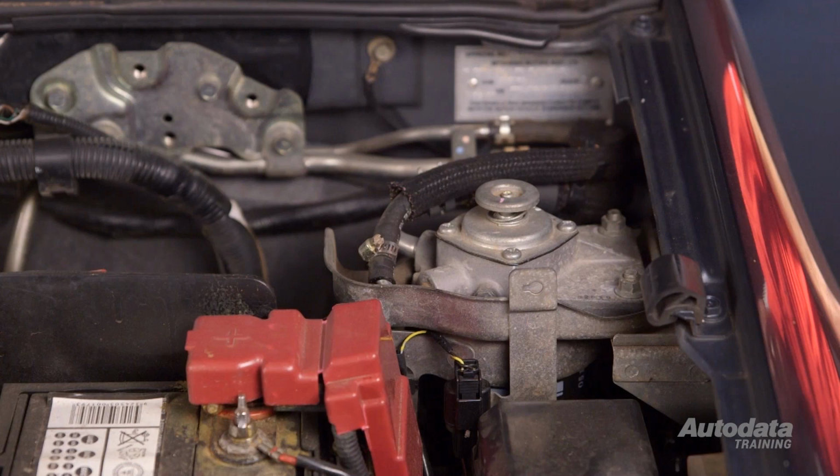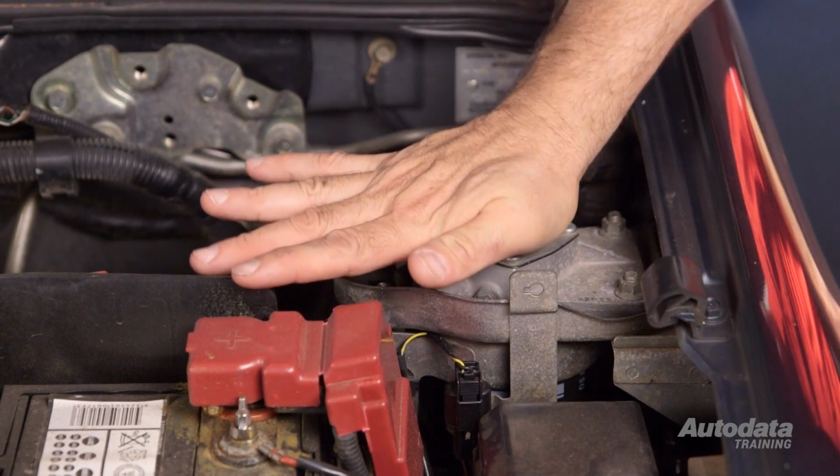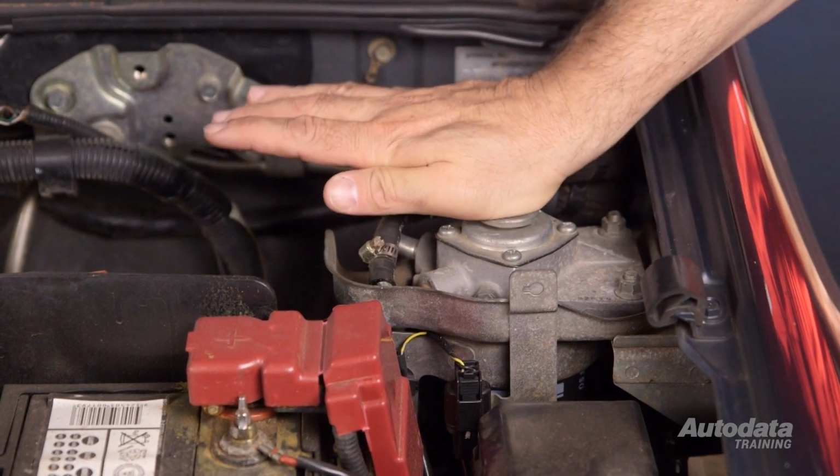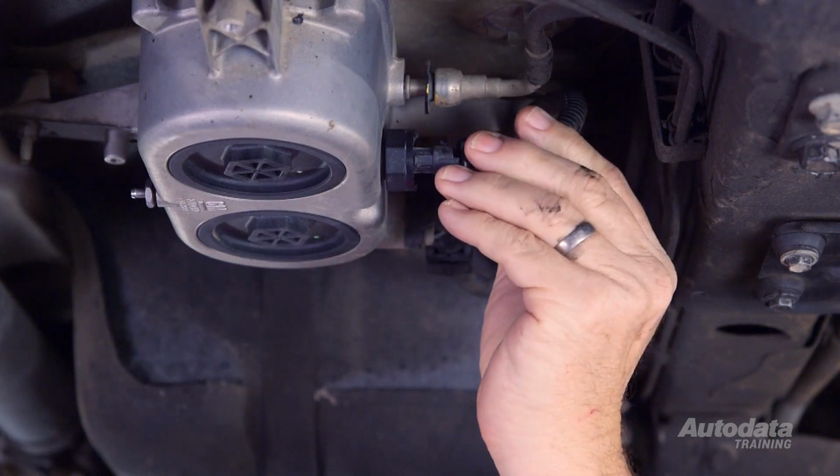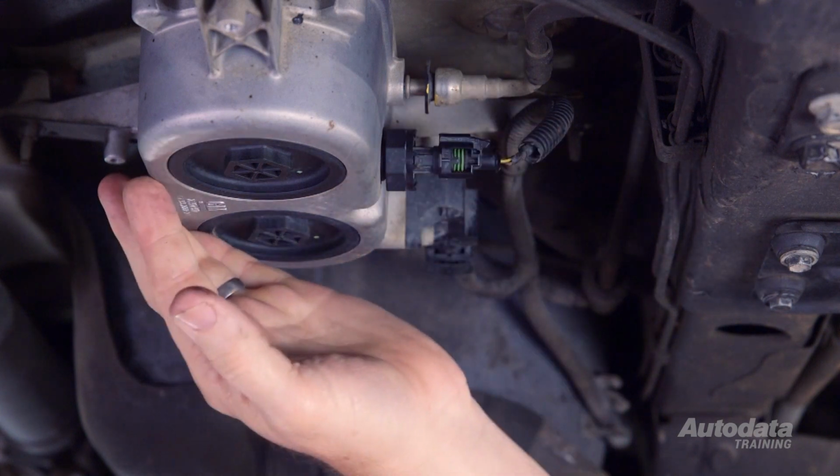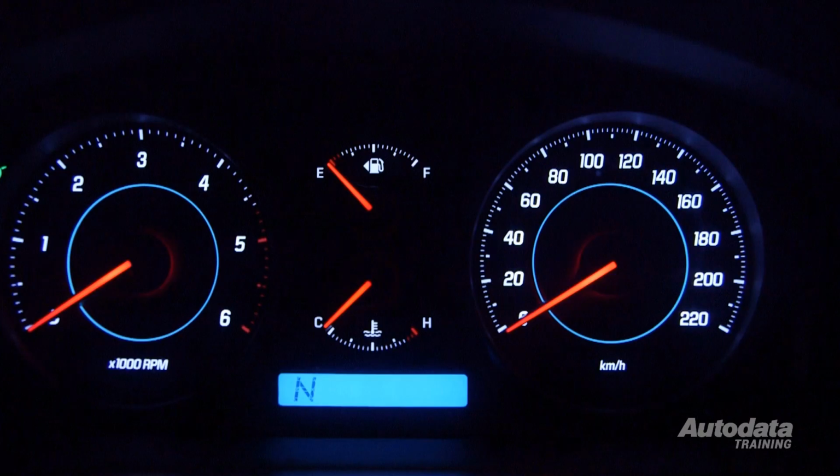From the pump, the fuel will travel to the filter. These will be in various locations. On this vehicle, it's underneath the floor. On others, it could be in the engine bay. This filter also has a hand priming pump. Some are even mounted on the engine itself. There is usually a water and fuel sensor in the filter. This will illuminate a warning in the instrument cluster when the water reaches a predetermined level.